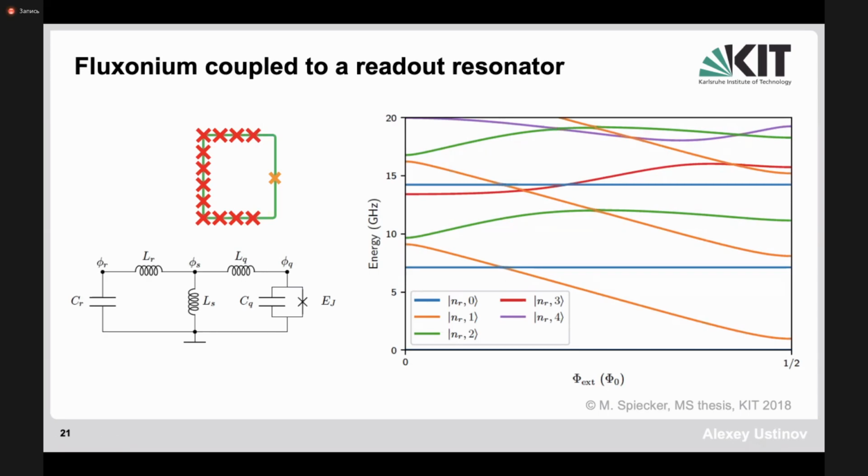So this is the harmonic oscillator. Now, this little inductor, which is sitting in the middle, couples two quantum systems. It couples this harmonic system on the left, which has equidistant energy levels shown here by these blue lines. And it couples then to an anharmonic oscillator, which is our fluxonium device, with a kind of soft parabola superposed with a cosine. And the diagonalization of the states of the parabola is shown here by these lines. You see this orange line, then you see the green line, and then you see also the red line, and so forth.